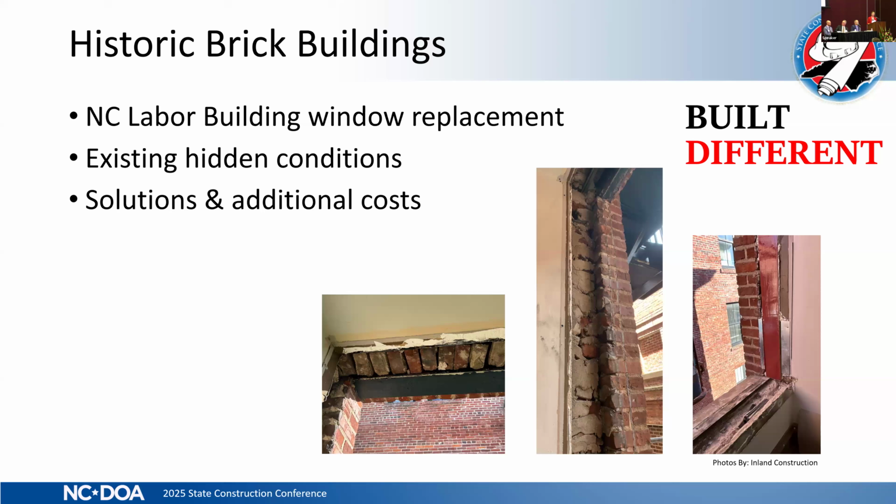New pressure-treated 2x lumber with metal brackets were installed to help fill these jamb spaces and to also give a solid structural member to attach the new windows to. Then additional liquid flashing was applied to the 2x, and light gauge sheet metal has been installed to help support those header bricks.